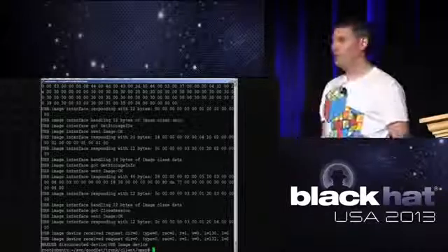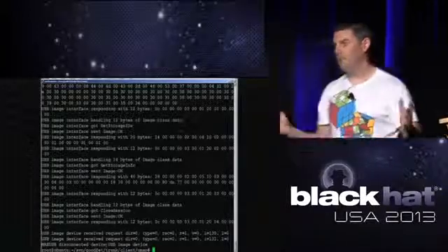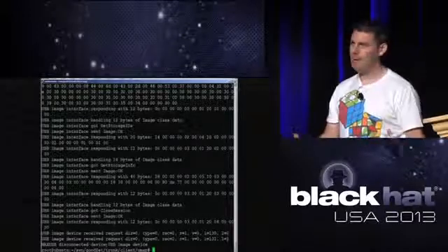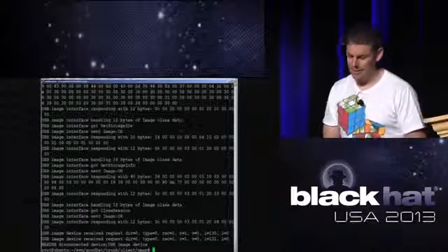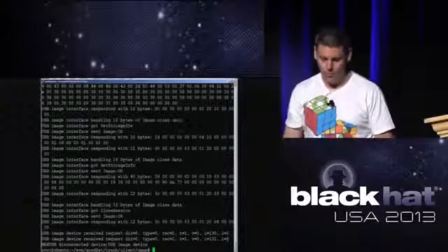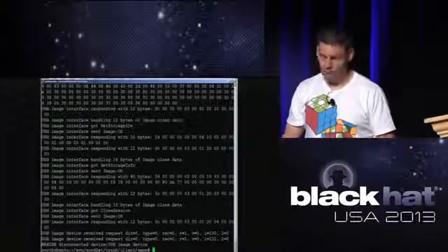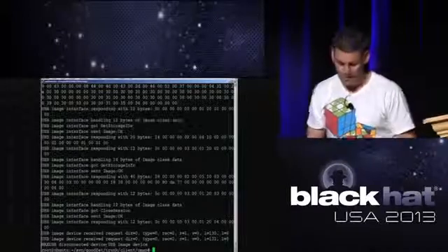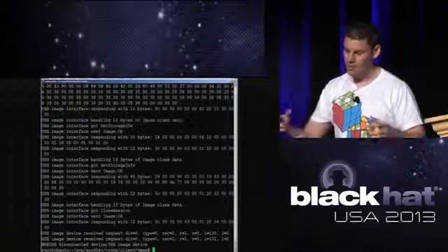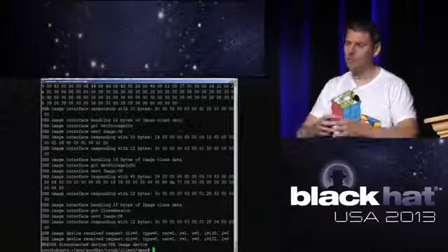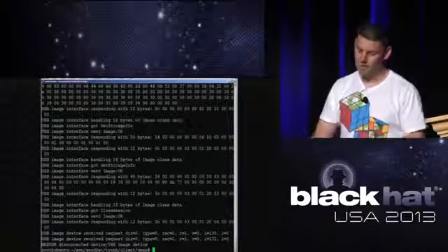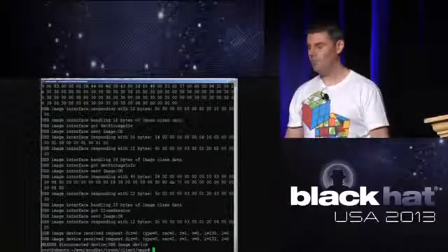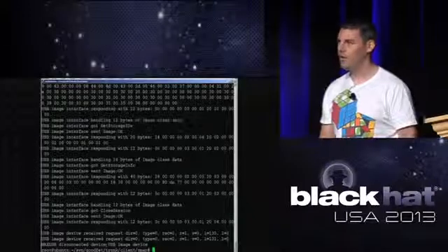And I've mentioned fuzzing a couple of times. I've done quite a bit of USB fuzzing in the past, and this new capability that FaceDancer has allowed me to have provides the capability to do much more comprehensive fuzzing now. So you identify what classes are supported, and then rather than the mutation-based fuzzing that I've done in the past, you can look at the spec and implement all your fuzz test cases based on the spec for the class of device that you want to fuzz.